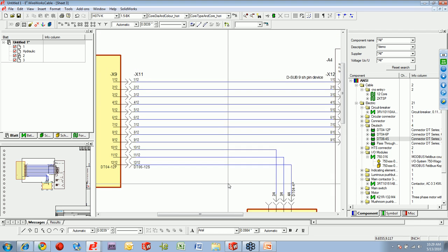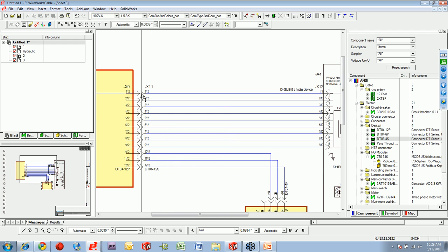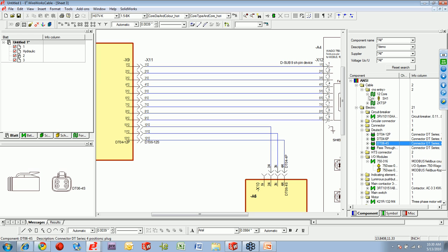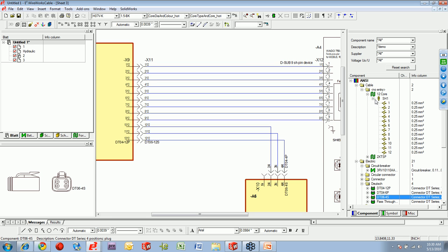So far we have some logical connections between the systems. We also have some connectors, which E3 of course paired up appropriately just to make sure we have the right one and make sure they end up in my bill of materials. What we don't have yet is some wiring. Now we can go apply individual wirings if we like, but more and more I'm seeing our customers deal with standard cables and working with those on a regular basis.